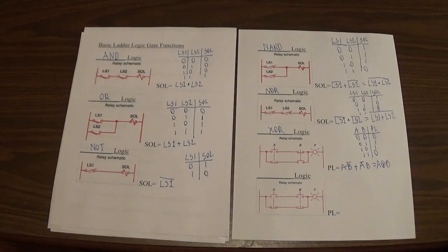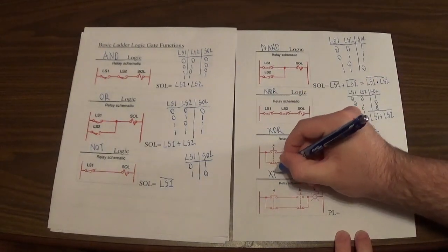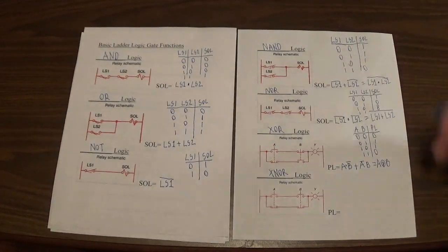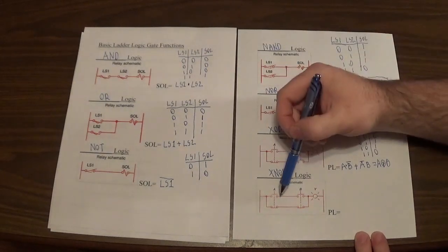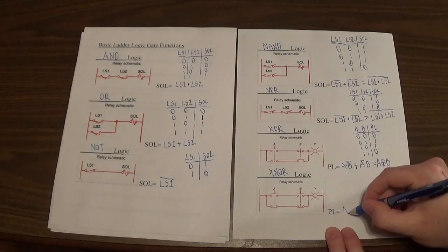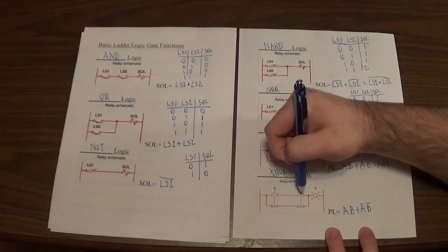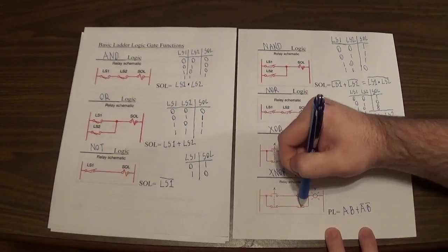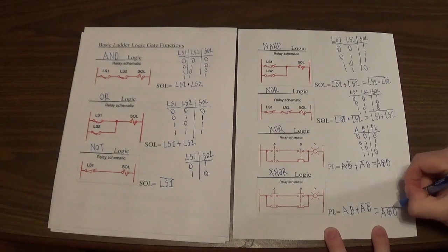Okay, so a little bit strange and unusual for the exclusive gates, but remember that's only for special applications where we use that. Alright, so down here's the exclusive NOR. It's basically the same kind of setup except a different arrangement of the open and closed. On the exclusive OR we had open, closed, closed, open. Here we have open, open, closed, closed to get the exclusive NOR operation. So if we write the expression, we have AB plus A naught B naught. They're open up here, so A and B, or A naught, B naught. Of course, we can write the equivalent here, which is A exclusively OR B naught.